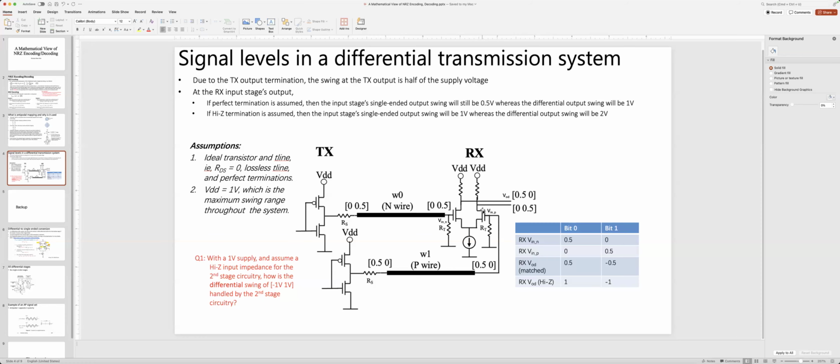And if we continue to use differential circuitry, we will need to double the silicon area, which is very expensive. So that's the reason why we usually use single-ended circuitry for the inner stages in op-amp and SerDes.